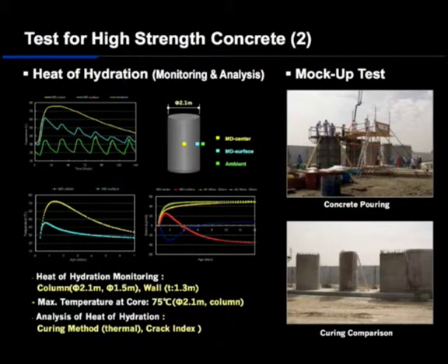Before finalization of the mix design, we did the mock-up test, a 2.1 meter concrete column and the hammerhead walls. We analyzed the heat of hydration, and through this analysis we designed the curing method. Inside the concrete, the maximum temperature was 75 degrees Celsius.